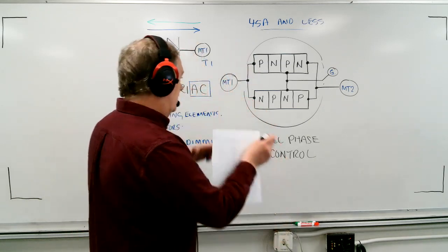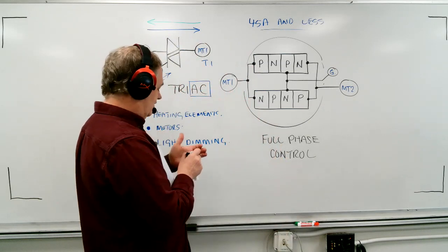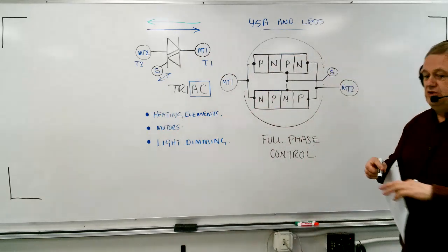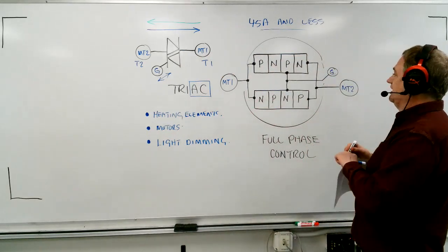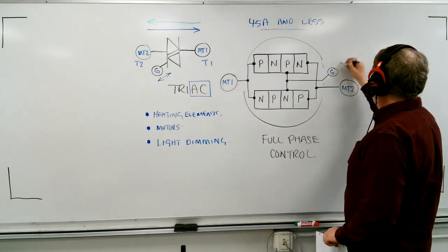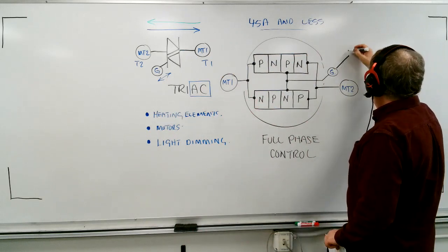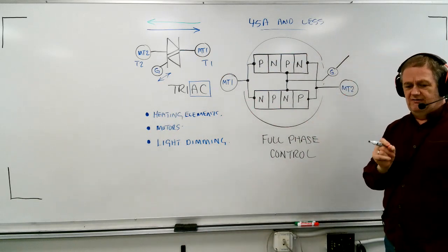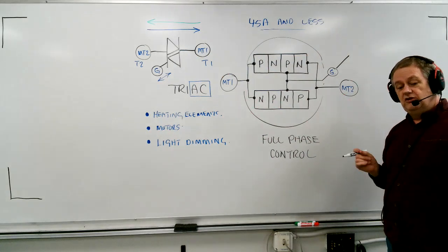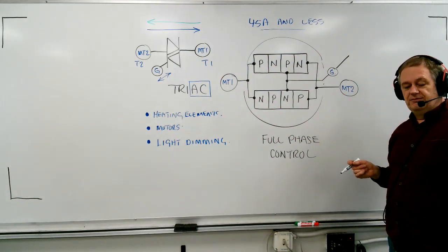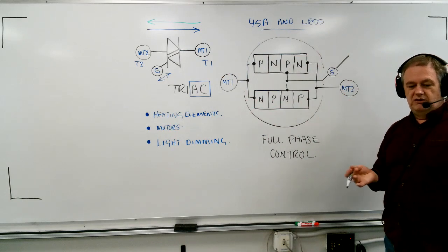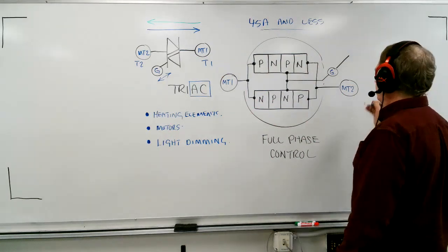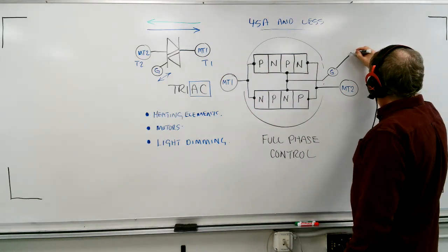Now, triacs are an interesting circuit. When you get into the triggering circuit, we need to use one particular type of triggering component that goes in series with the gate. And that component is there to control to a very, very small level the amount of gate current. Now we can also use the same component in SCRs for triggering, although in many cases we're okay just with the resistors or resistor capacitor, but this lowers even more the amount of current. This device looks like this.